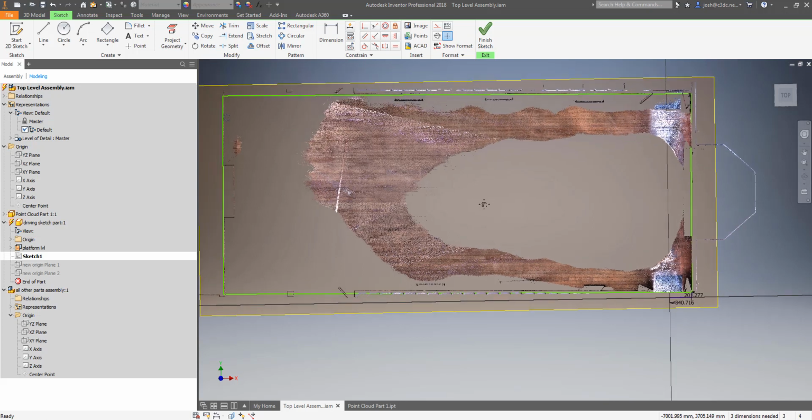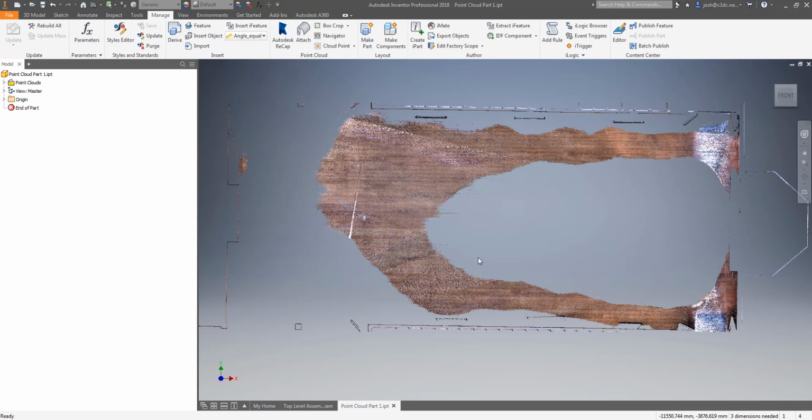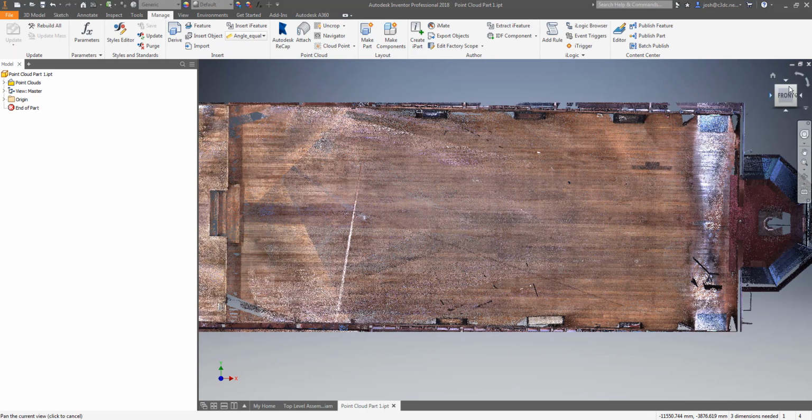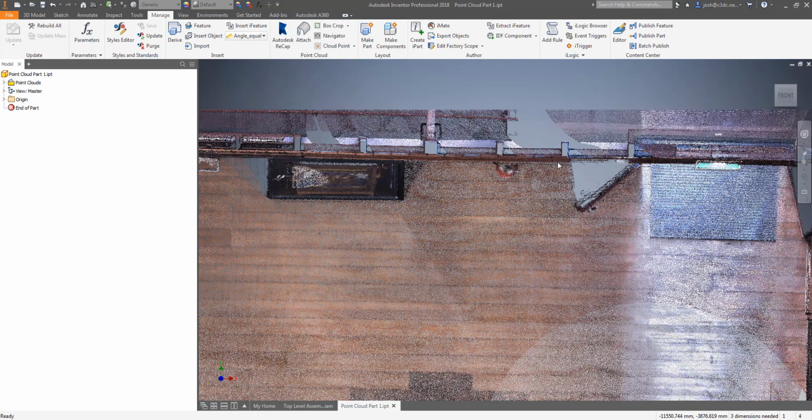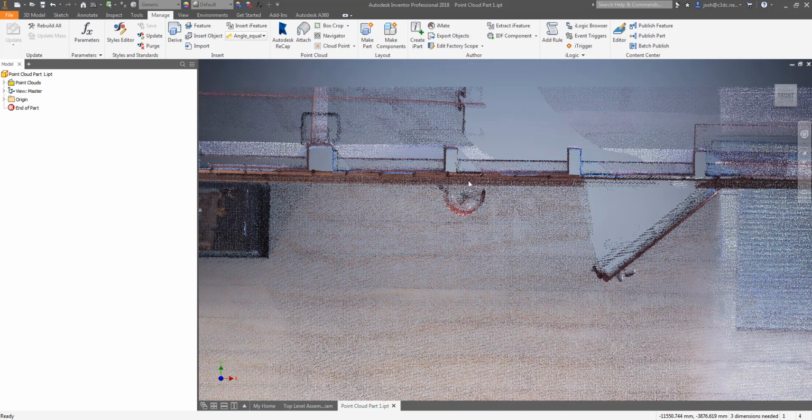Another reason that detail is often difficult to make out in a point cloud when viewed from one angle like the top view is that what you are looking at is a feature that is not straight or perfectly vertical or horizontal, like this wall. Who would have guessed that of a 130-plus-year-old church, huh? Aside from being bent and out of square at this level, in this direction, it is also bent and out of square in the vertical plane. So when viewed like this from the top view, what you are seeing is the points that make up that whole wall from top to bottom, and this is the very confusing result.